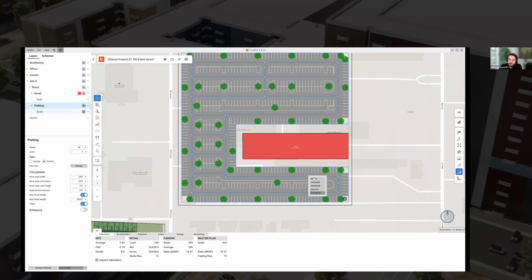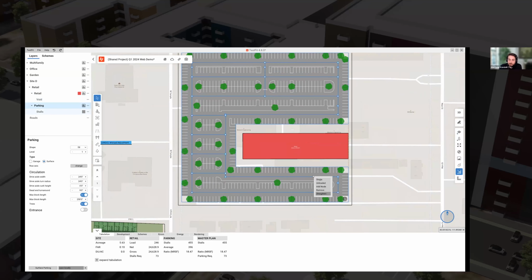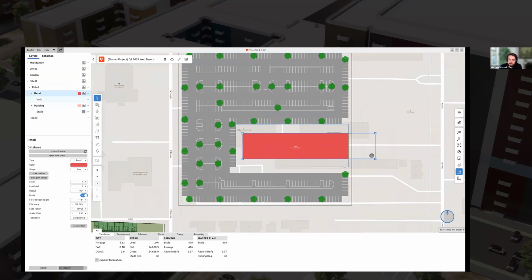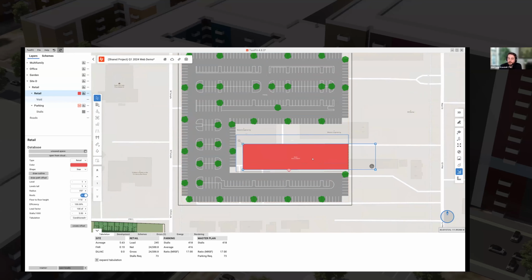I can right click on that node now. I can either click unload, which removes all parking from both sides, or I can right click and make it single loaded. Right now, I'll flip that back over. So now it gives us a bit more flexibility. I can start to push that over where that area is. And around this space, we also have a void space being shown. But you can see now we can control a bit more detail of how we're drawing that, as well as manually start to define some of these roads.